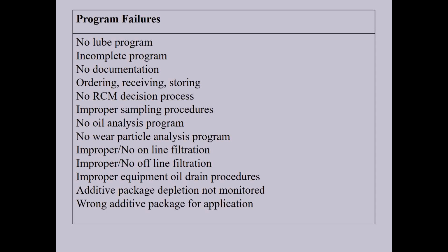Not having an oil analysis program. Every industrial plant should be sending some samples off to be analyzed, or buy equipment to analyze them. No wear particle analysis program. What are the wear particles and where are they coming from? Improper oil drain procedures. So you can see a lot of program features here. Wrong additive package for the application. All things that we can cover later on with the training.